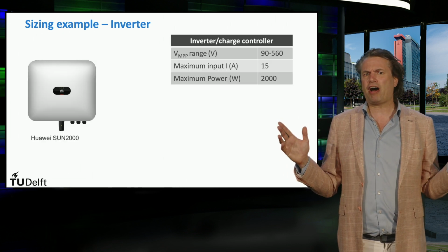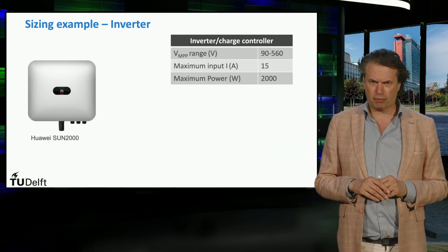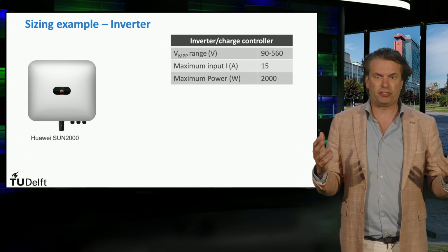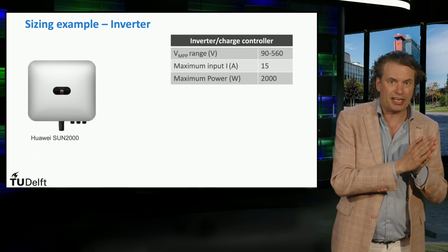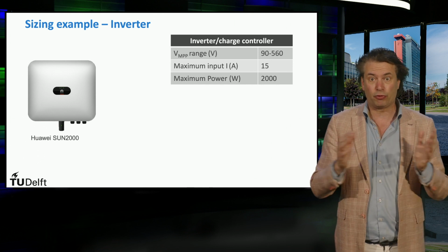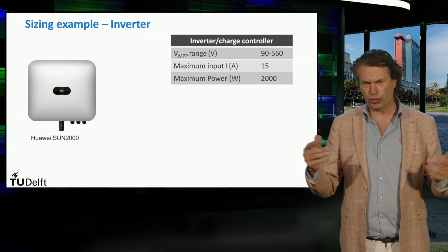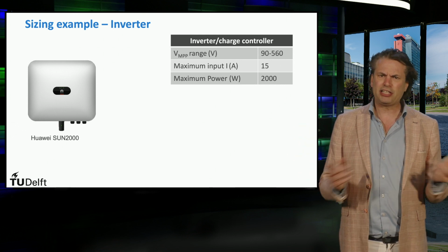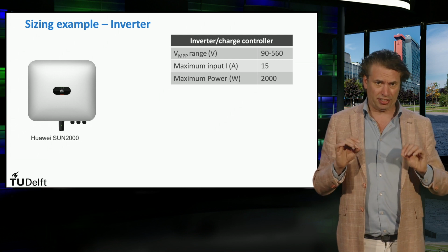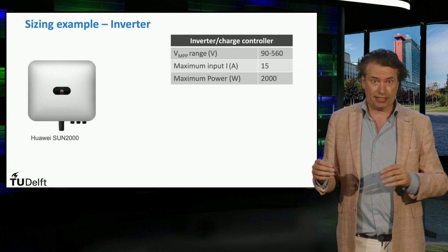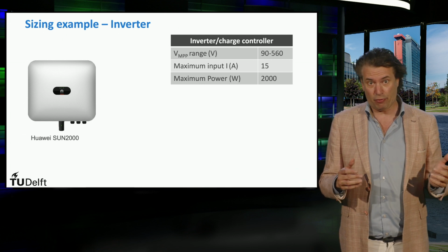Now I must clarify one thing about the grid-connected PV system. Usually the amount of PV panels or the rating of PV panels need not be exactly as per the load requirements, like it will be for the standalone PV system. We will discuss this in the next video. This is because any excess or deficit of PV power can be compensated by the grid that is present in the scenario anyway.